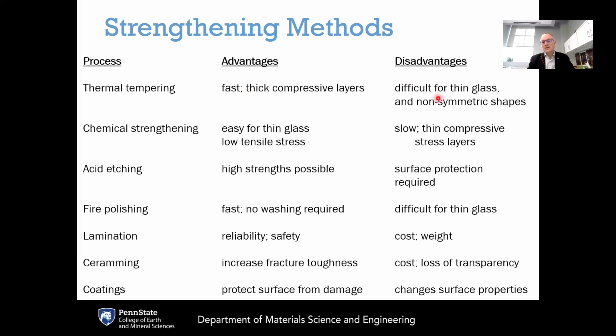Disadvantages are that it is difficult to accomplish this for thin glass or for any kind of non-plate geometry. It also requires a glass composition that has a high enough thermal expansion coefficient to be able to get the mismatch in thermal strain.